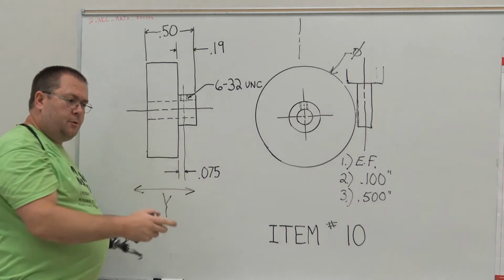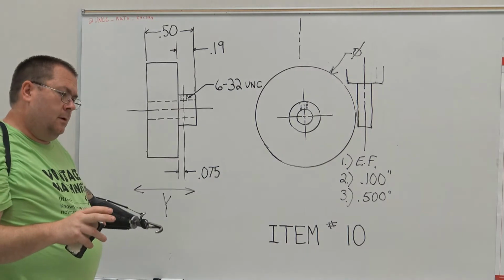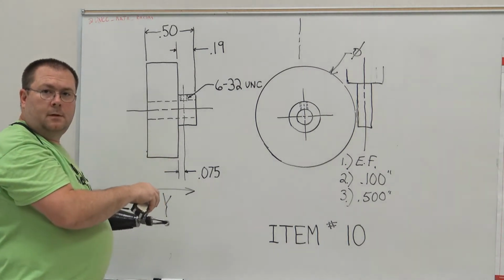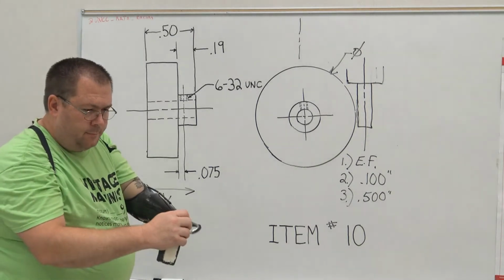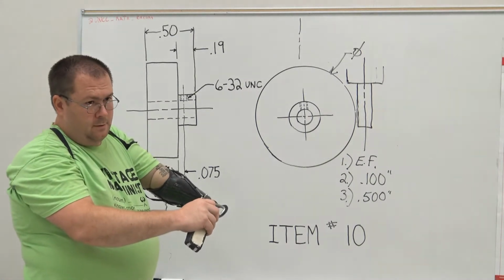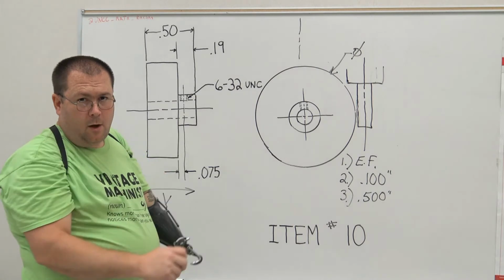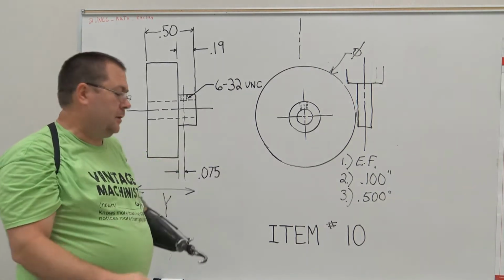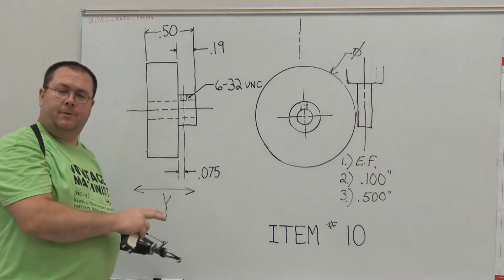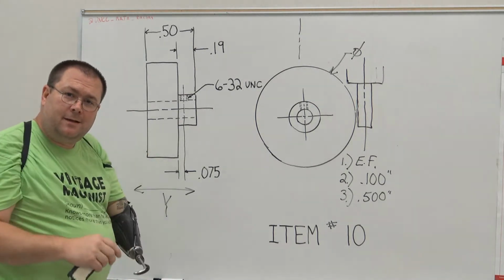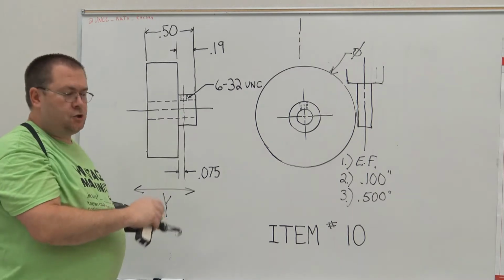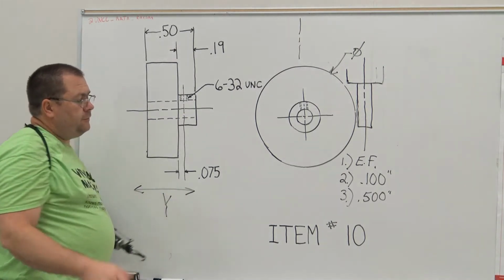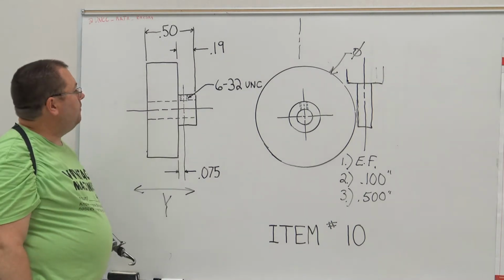Okay? Because no matter what you do, you're not going to be able to make perfect parts. Now I have students come up and say, well, look, Mr. Bryan, I can't get this thing to read off 500 thousandths. That was what I was shooting for. Look how perfect that is. I can always come up with something, a measuring device, that's going to measure it more accurately and show you that it's not perfect. Okay? Surface finish, lots of things go into that.